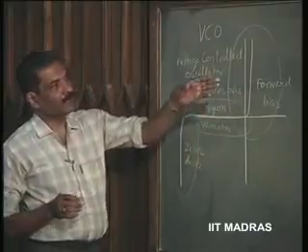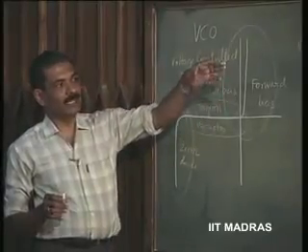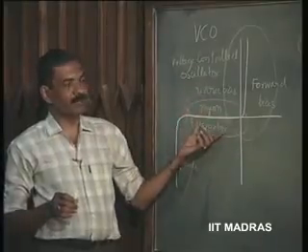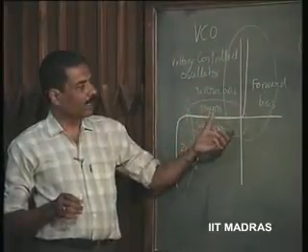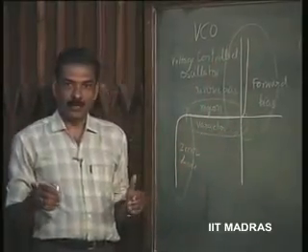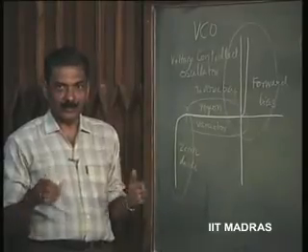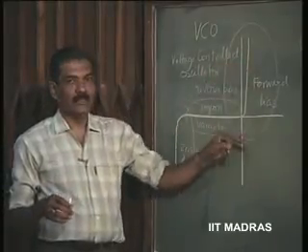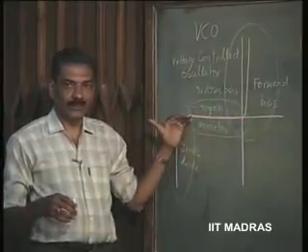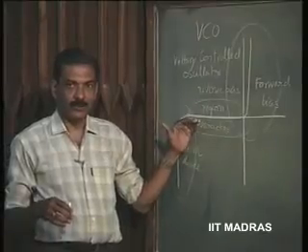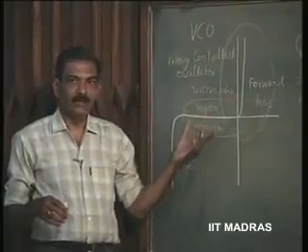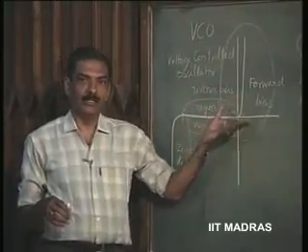Here he will maximize the ratio between C max to C min, and specify what value of maximum capacitance it has. Then he will say at what forward current it has to be operated, what is the average forward current, repetitive forward current, all these things when it is being used as a rectifier diode. What should be the peak inverse voltage rating of this if it is to be used as a rectifier diode? These are the different ratings. So, different diodes have different emphasis on the ratings.